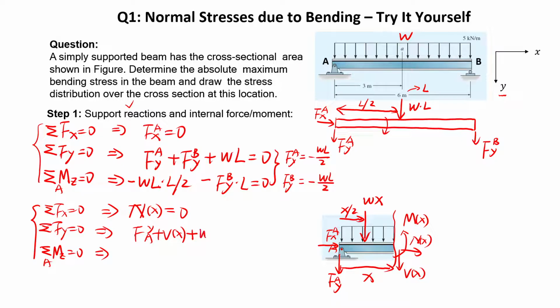Okay, so the force balance gives Wx equal to 0, and this gives us one equation. Using the moment balance we will get another equation. Wx, this concentrated load, is trying to push it clockwise, so there's a minus sign here: Wx times x over 2. That's the moment generated by this force.